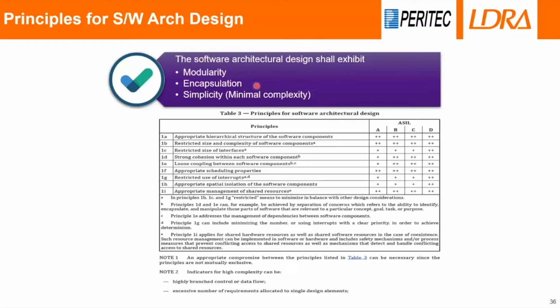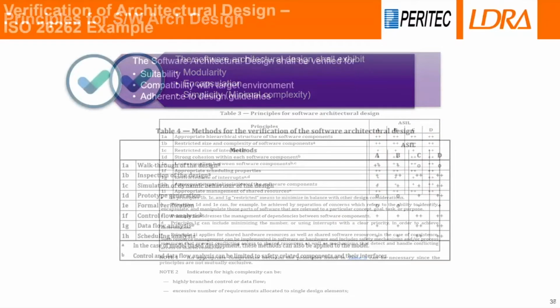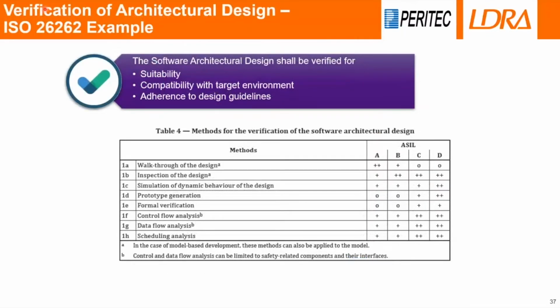It also gives a table which lists out a lot of design principles, and most of these design principles are highly recommended for ASIL D, highly critical applications, and for less critical applications there are a few recommendations and a few of the things are highly recommended. And looking at the verification activity for the design, you can see simulation of the design is a recommendation, but it is highly recommended for ASIL D.